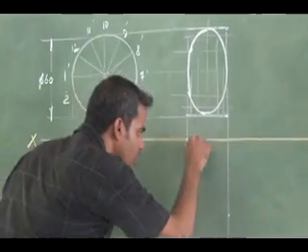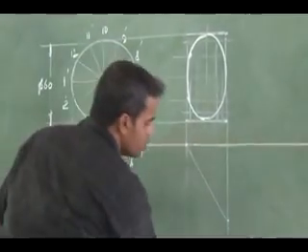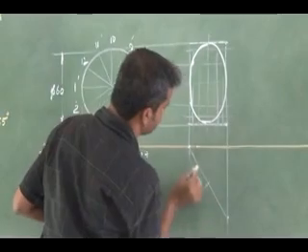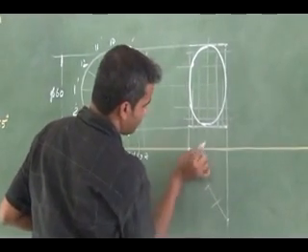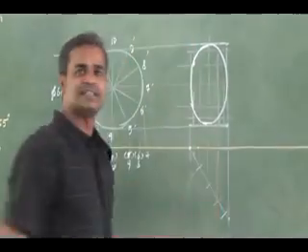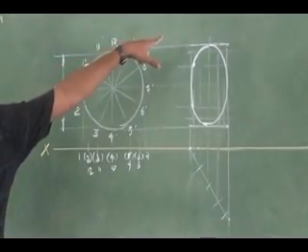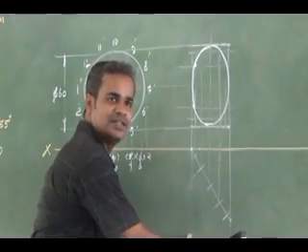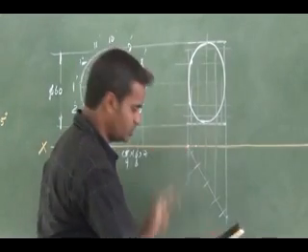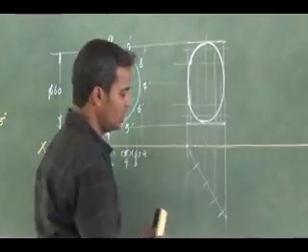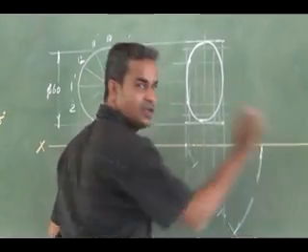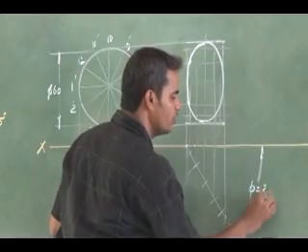Here it is going to be my tilted top view, the first step. So you can mark the various locations here. This I have projected, and I have got the ellipse. The distance between the projectors is going to be my minor axis, 30. So I can tilt my top view within this 30 mm length, right? Whatever inclination it has, it is going to be my inclination of the surface with respect to the vertical plane. This is the phi you are asked to find out.